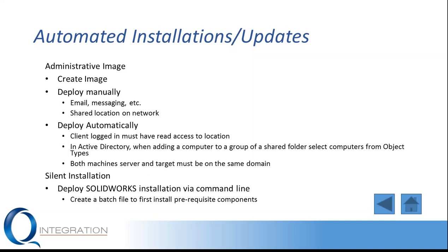We can also choose to silently install these SolidWorks products, and so we can deploy these installations via command line. Now one thing to keep in mind with this is we do need to create a batch file to install the prerequisite components first, as this is not included with the command line installation for SolidWorks products. And a great resource there is the installation guide. There's a whole section dedicated to showing you step-by-step how to develop that command line installation.